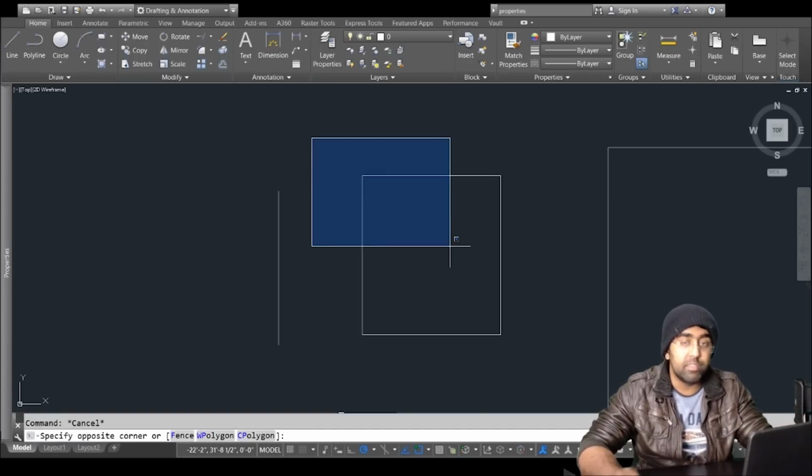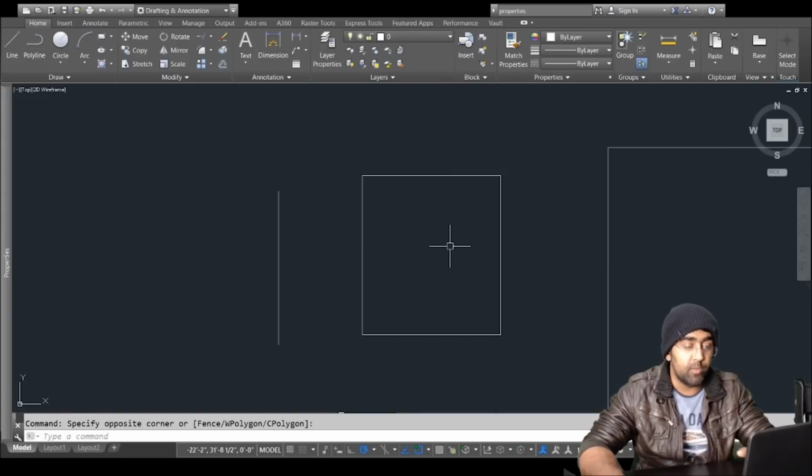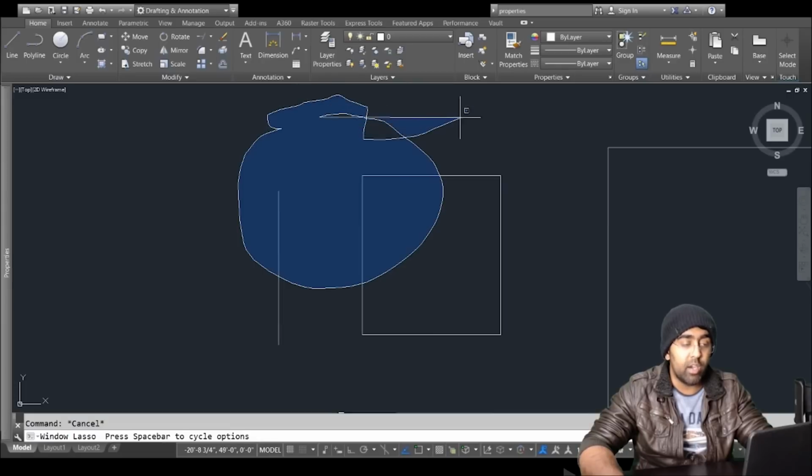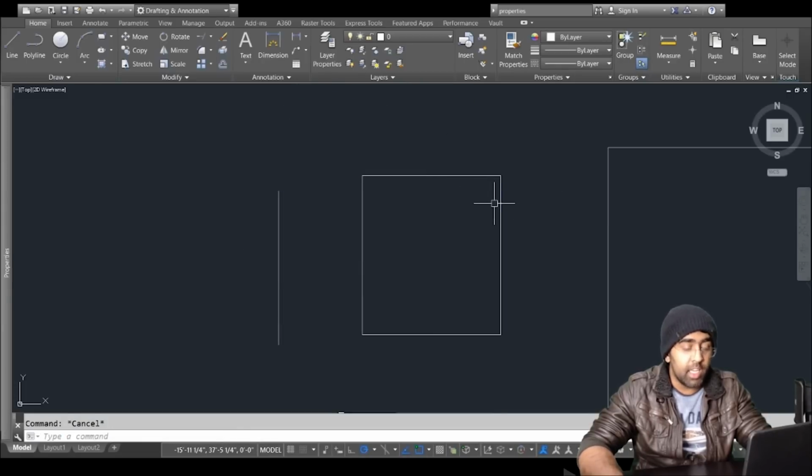So what is the difference between the green and blue windows? And there's another selection: if you click and hold the button, you can do the lasso selection. If you click and hold your cursor to the right and move, it's the same lasso selection, but it is a different kind of selection. Let me explain what it is. If I click here and move my cursor to the left, it gives me a green window, and if I click again, I will select that rectangle.